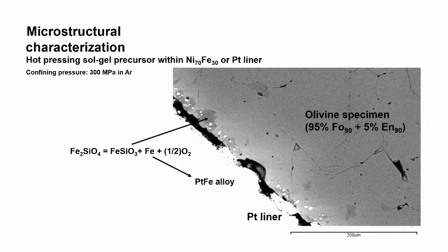The first step of this work is sample preparation, and we need to find an approach to control the grain size of olivine samples. To avoid complication of natural precursors, we hot-pressed powder prepared from laboratory reagents by the solution gelation method. The synthetic sample has a narrow distribution of grain size and well-controlled chemical composition.